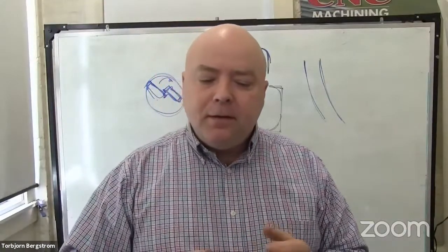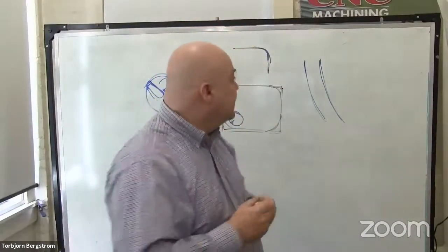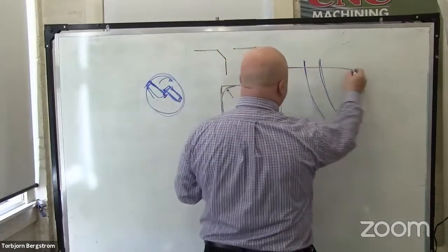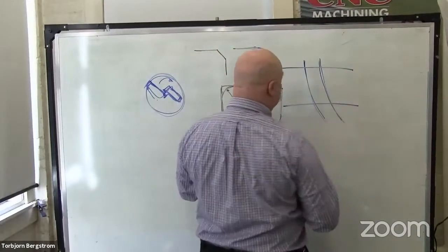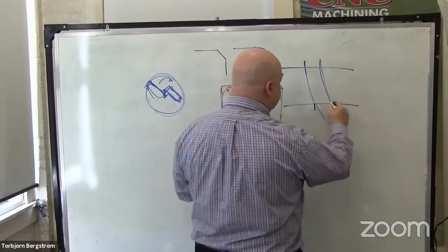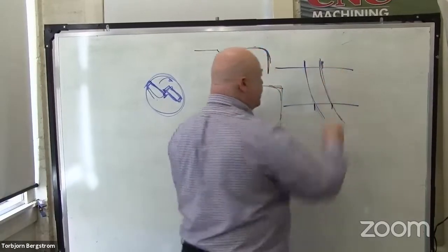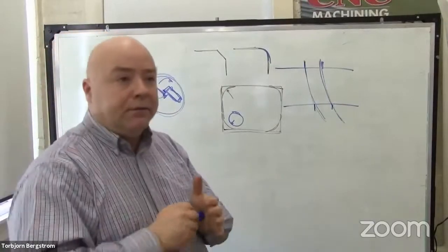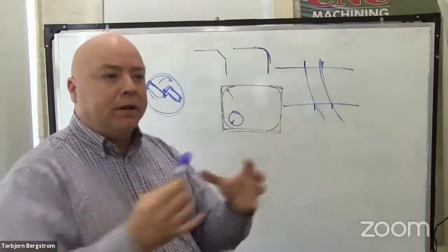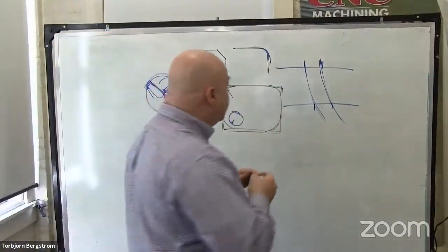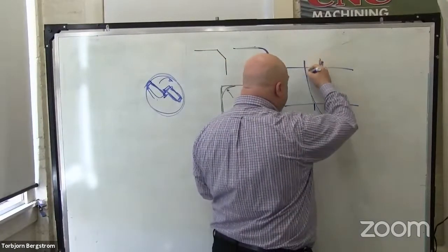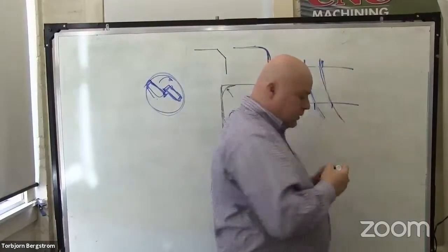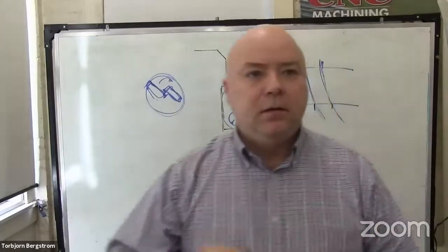Goes out of tolerance? Yeah, all of those things happen. If you're drilling through a part, so if there's a top and a bottom, the hole at this end won't have the same location as the hole at this end. That's problematic if you need stuff to line up when you bolt it together. But if it bends too much, the drill breaks. How do you keep the drill from breaking?